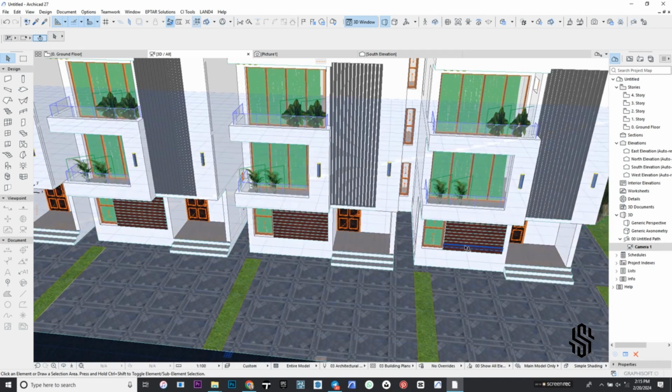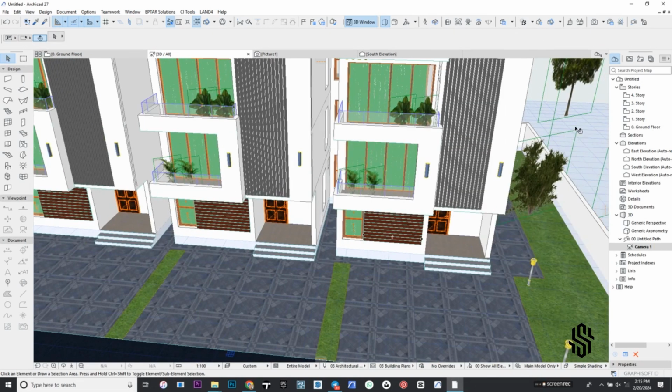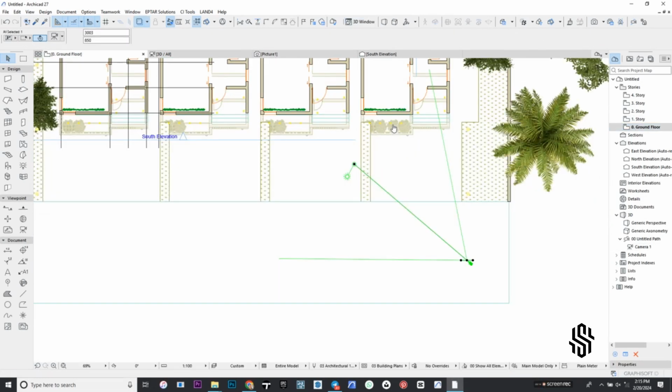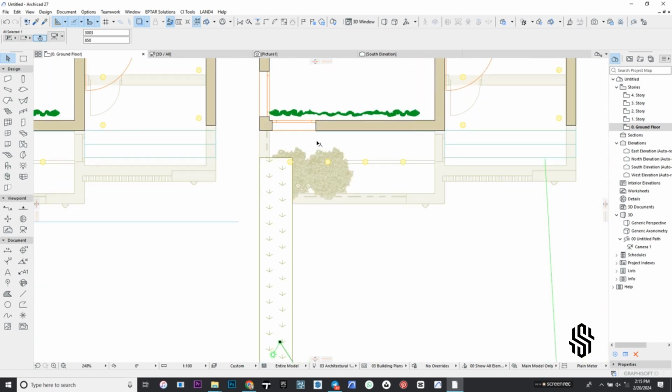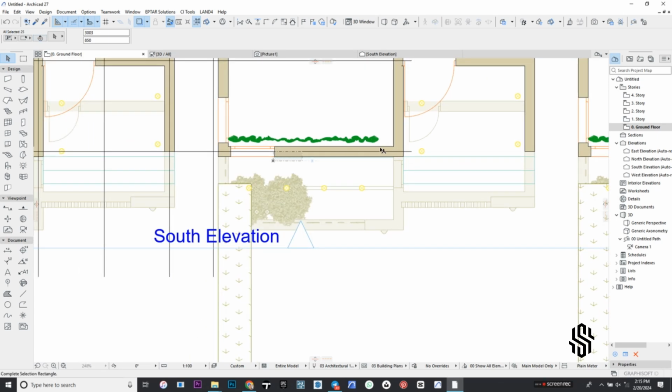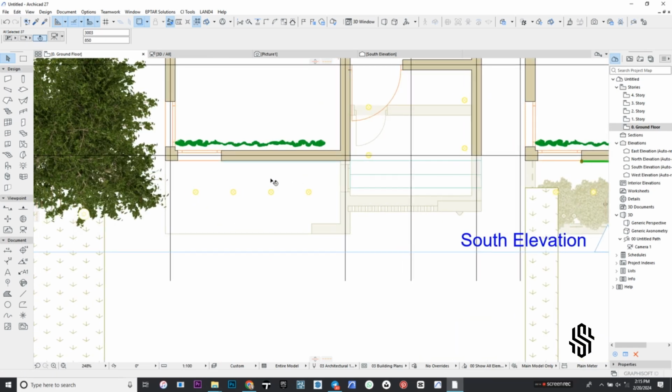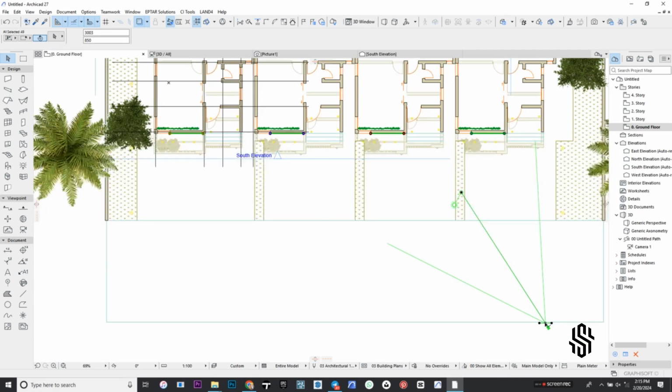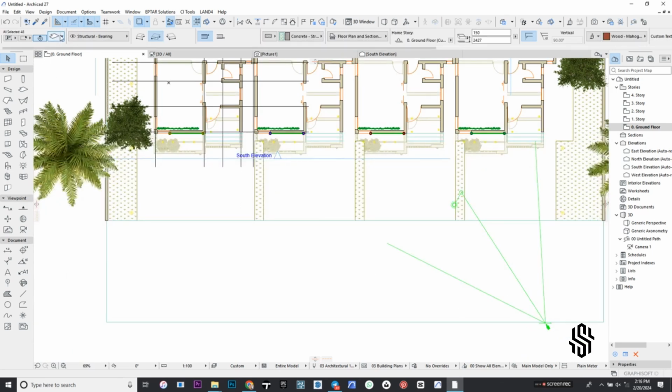Next, I would like to select the slabs, but they are 1-1, so I can't select them individually. I'll hold Shift and Spacebar to select just the slabs there. Shift and Spacebar to select them. I'll swipe to the other side, Shift and Spacebar, and select it. Go to the last part, Shift and Spacebar, and select it. Because my camera is selected, I won't be able to go to the settings, so I will deselect the camera, go to slab settings, and change them to wood 1.